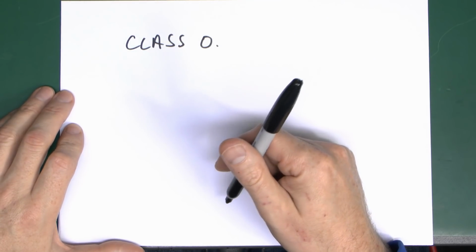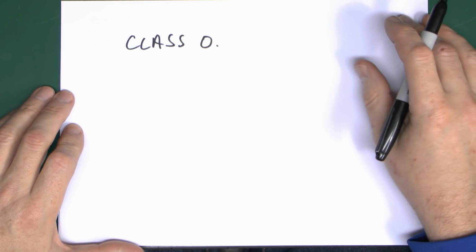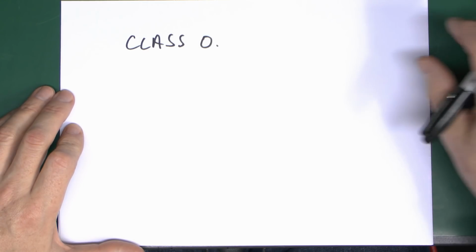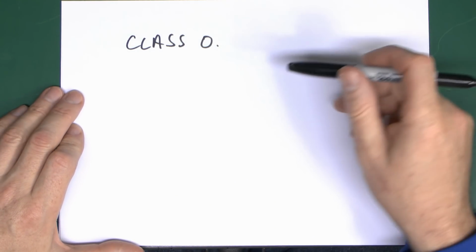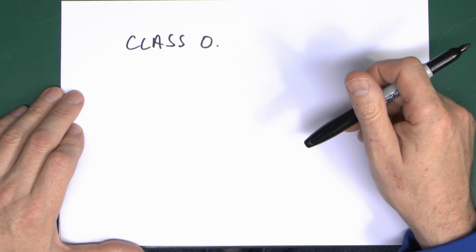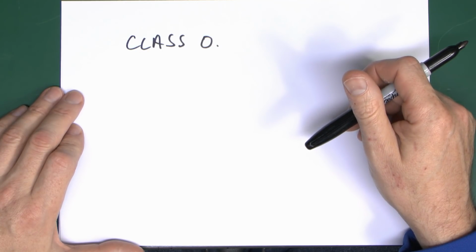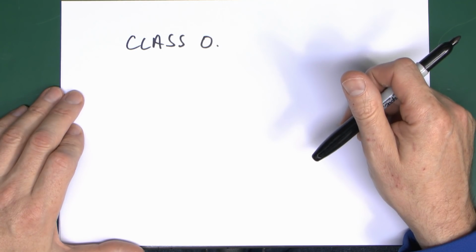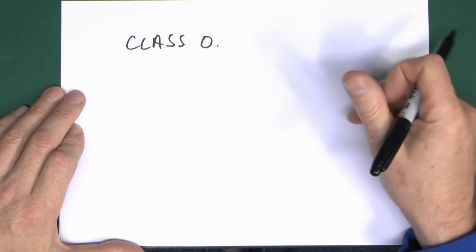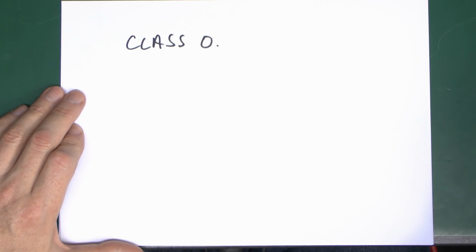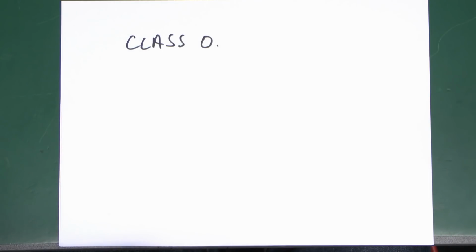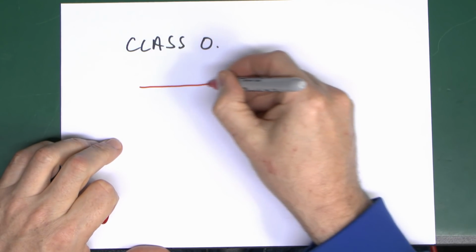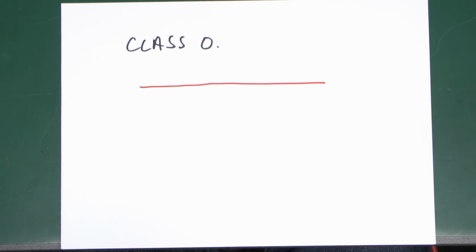So Class 0, this one you really shouldn't find anymore because it was discouraged and deleted a very long time ago. Class 0 is defined in the standard as equipment with basic insulation as provision for basic protection and no provisions for fault protection. So essentially what you're going to have there is your live conductor, so there's your copper core of the cable.